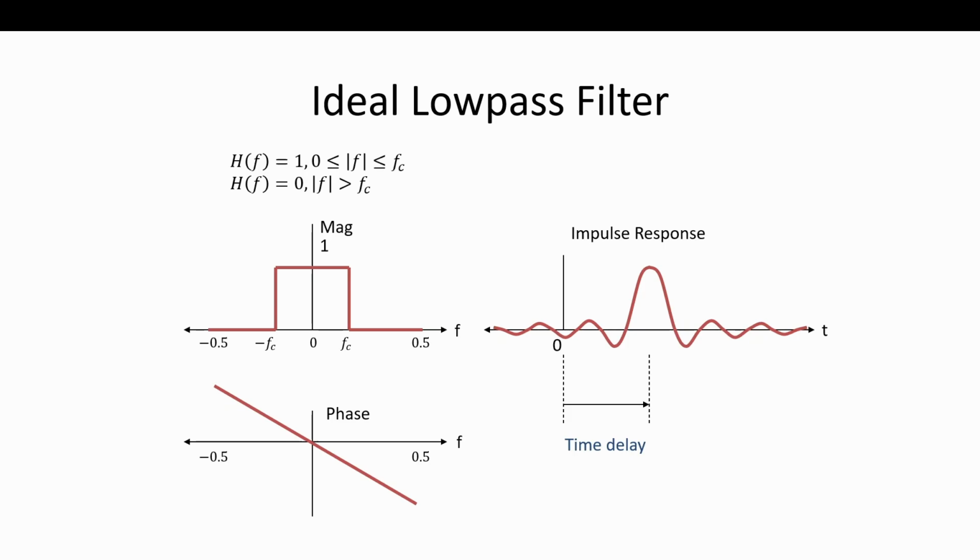And the cool takeaway there is that everyone can relate to once they've seen the Fourier series expansion. The Fourier series expansion takes some arbitrary waveform, whatever it may be, and you can decompose it into a sum of different individual frequencies. So we create a really nice waveform, perhaps for wireless comm, and we want no ISI and things like that, and it has all these different frequency components.